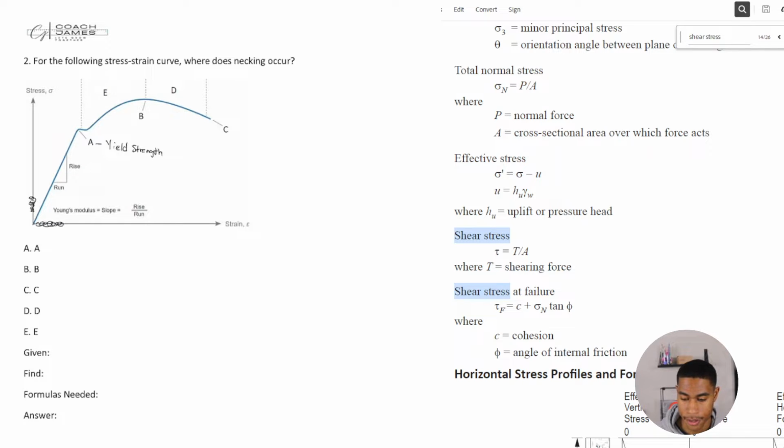And so if you've ever, let's say you've had a paper clip, right? You can pull on that, you can push or pull on that paper clip until a certain point. But if you really pull it and pull it out of its spiral loop per se, then there's no way to get it back in that original shape. And so that's the point at which you're hitting your yield strength.